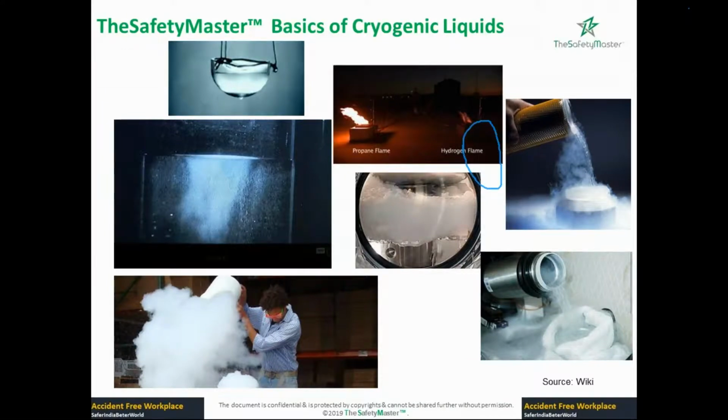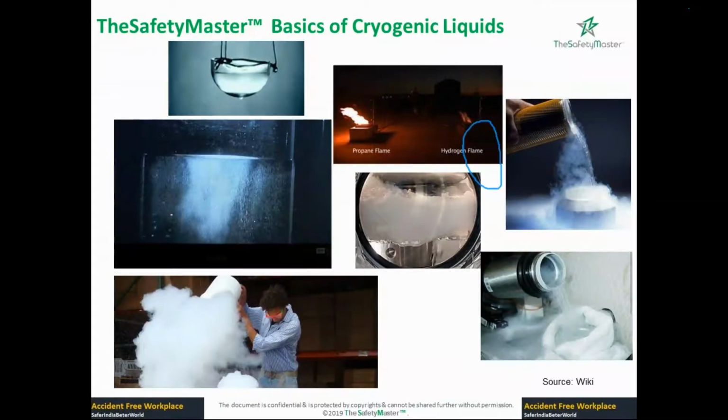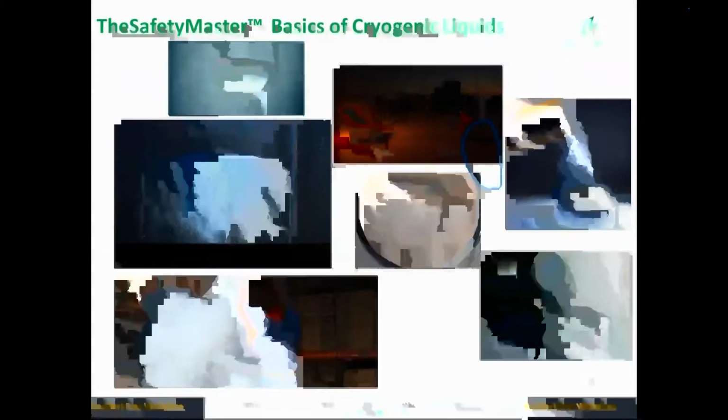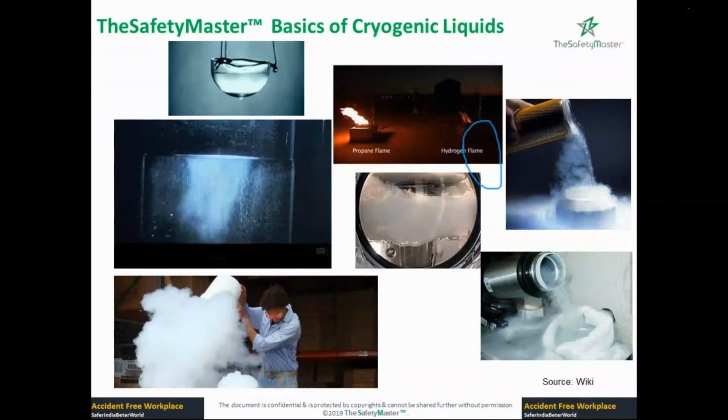If your temperature is high, the density is less. So when handling it in an air compressor, a cold temperature is more efficient, but a warm temperature may not be efficient. Those are some of the issues.